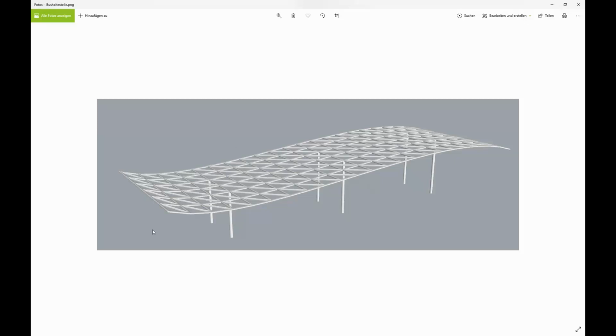The shape of the roof is basically a curve if you cut through the roof. And the shape can vary. So it could be longer, the width could change, the height of the roof could be different. Then the area of the roof should be cut into these triangle elements, so that later on we can place plain glass panels into them, for example. So this is the goal: a basically parametric bus station or bus depot roof that should be created in Grasshopper.